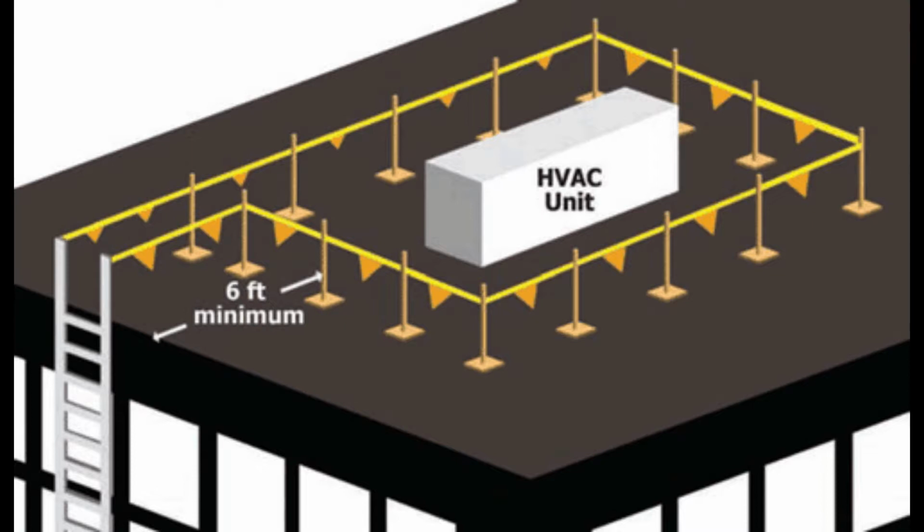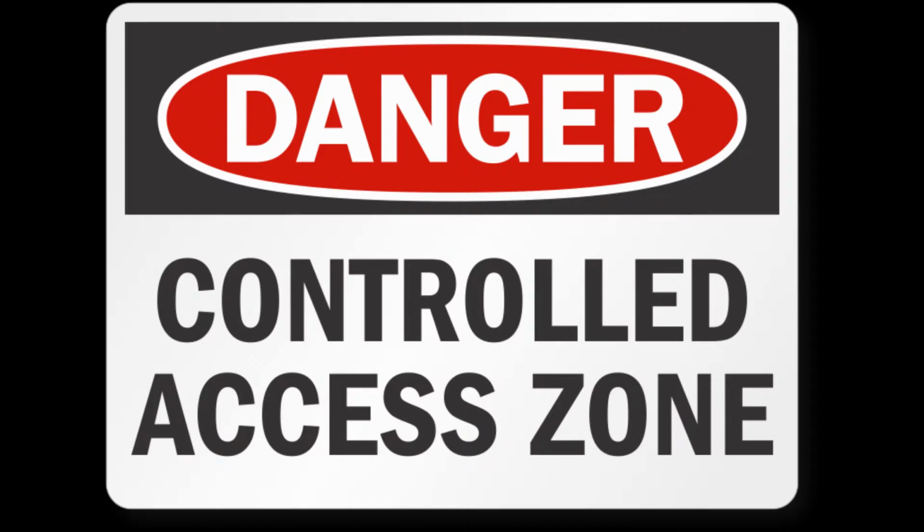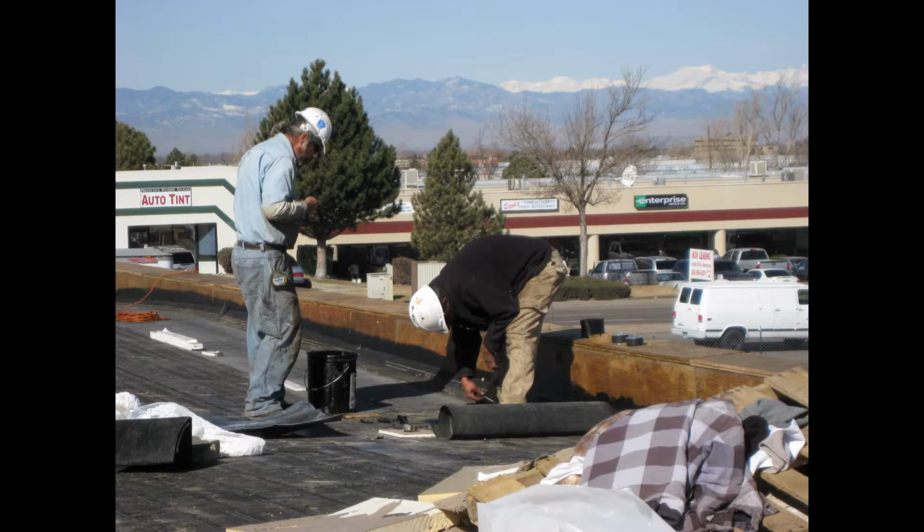On floors and roofs where guardrail systems are not in place prior to the beginning of overhand bricklaying operations, controlled access zones shall be enlarged as necessary to enclose all points of access, material handling areas, and storage areas. On floors and roofs where guardrail systems are in place but need to be removed to allow overhand bricklaying work or leading edge work to take place, only that portion of the guardrail system needed to accomplish that day's work shall be removed.